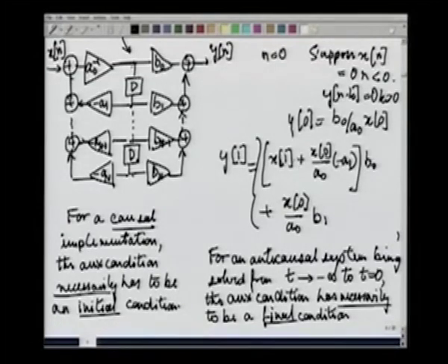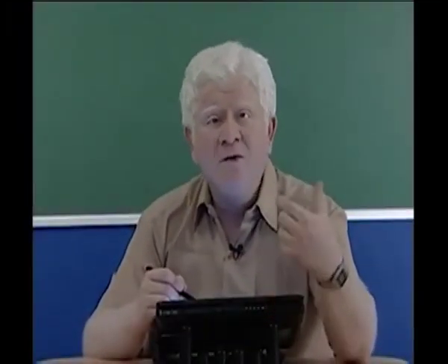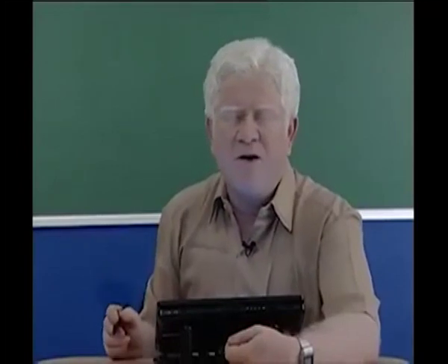It has incorporated the value of x 1, it has incorporated the delayed functions that have arisen in the meantime. Now clearly you can see y 1 uses both x 1 and x 0. Y 2 will use x 1, x 0 and x 2 and so on, so that after n instants, where n is the order of the system, the past n values of x will come into the picture, and even older values will come into the picture because of the autoregressive nature of these blocks on the left side, and the system completely starts functioning as it is supposed to.